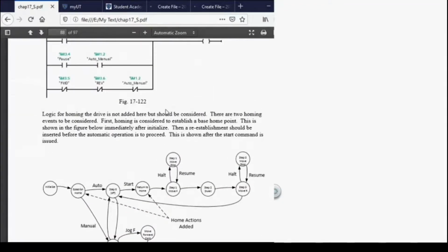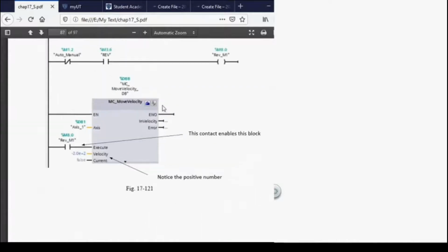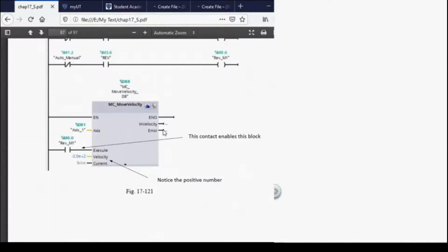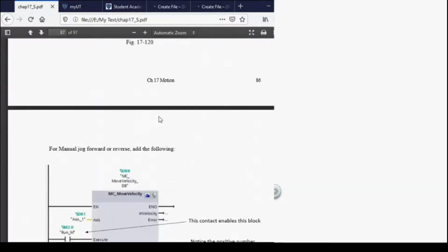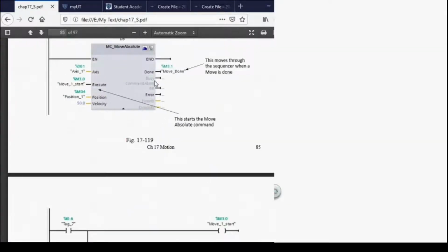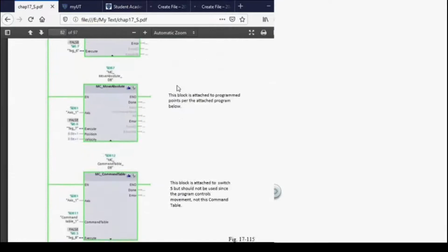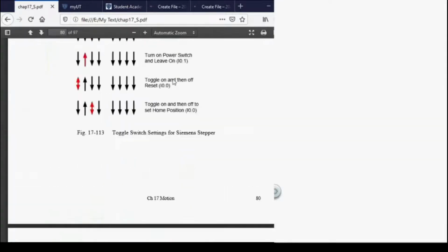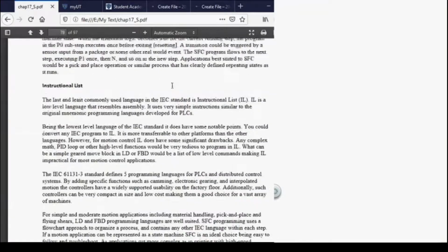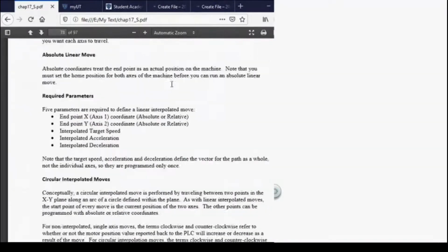Whereas the Siemens one, if you're done, the done bit comes on. So if I do a specific action and it's done, the done bit comes on. Here, there's no move velocity, but basically, if I tell a move absolute, the move is done right there. But with Siemens, with Allen Bradley, it's not the case. Allen Bradley has a variety of bits, and I'm going to go back up here and I'm going to show you those bits in a second.